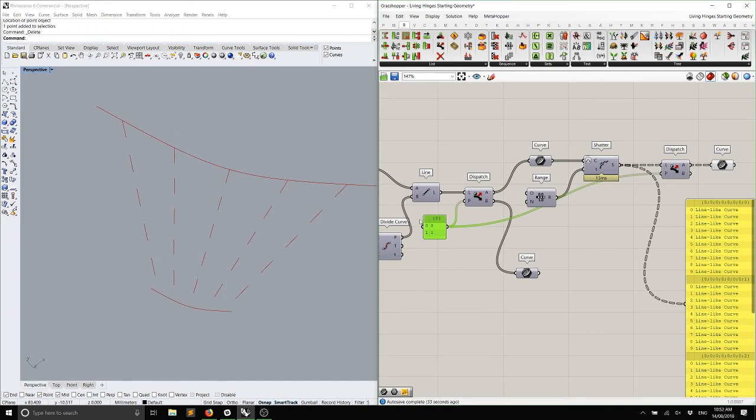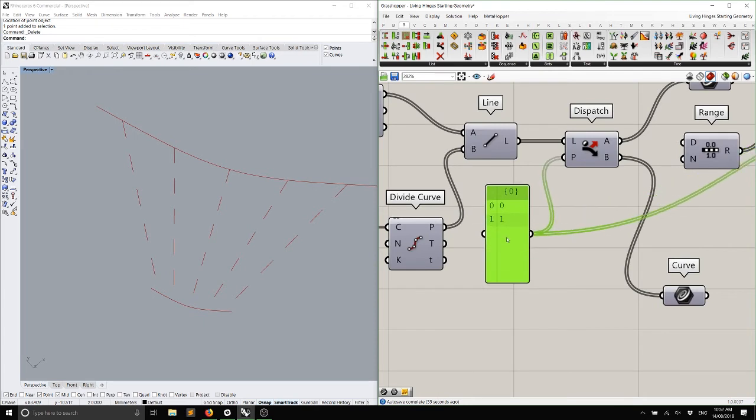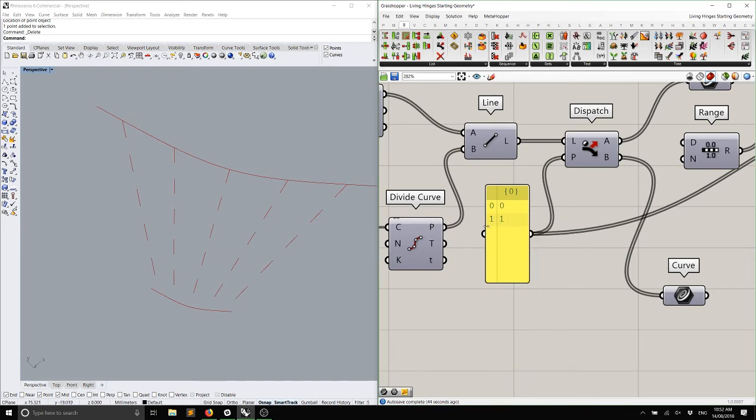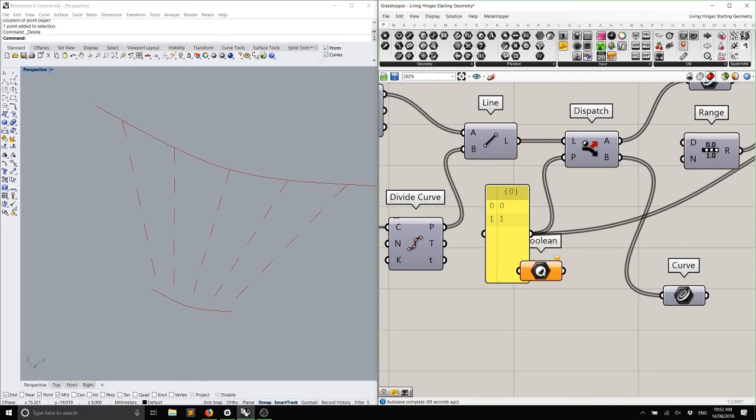Okay, so that means this panel here has got something in it that isn't a Boolean. Have you right-clicked the panel and made sure that multi-line data is off? Is one of the lines empty? Nope. If you double-click into it, is there a space after one of the zeros and ones? Probably just a Mac. Yeah, I think it's a Mac. Okay, then in that case, another way of doing this is getting a Boolean component.